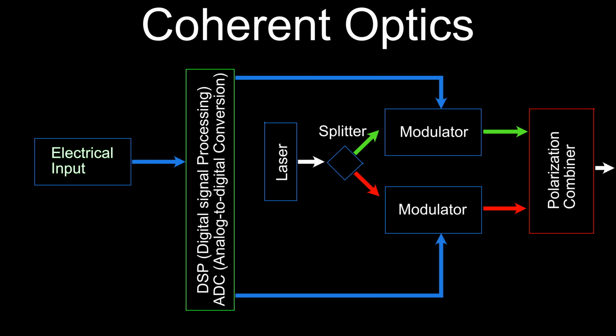We're undergoing a similar shift in the optical world with something called coherent optics. Right now, optics are using PAM encoding and function much in the same way as GigE does, only with an optical medium. However, coherent optics use a laser that produces a fixed beam at a specific wavelength. That light is then split and sent into 2 modulators that use some amazing techniques to encode the bit stream onto them. Then they are recombined into a phase-shifted version of the same wavelength.